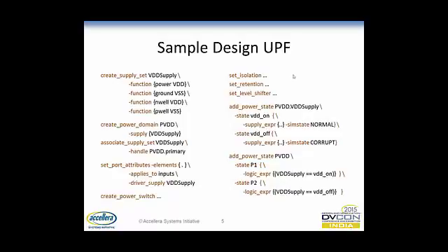So this is in Design UPF. In a UPF, you create some supply sets and define what the different powers or supplies are in that particular set, like power, ground, N-well supply, P-well supply, and then create a domain and associate the respective supply set with that particular power domain.